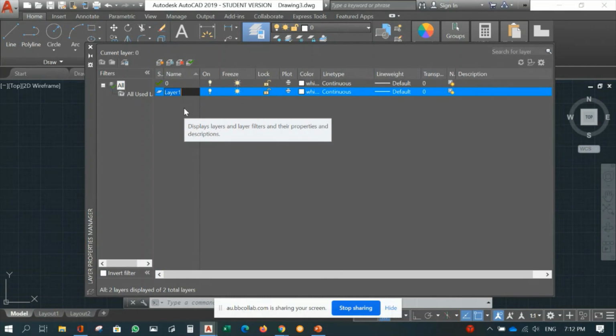This is very important, especially when you think of editing the drawing. Most important, with layers we can also apply the line width by using colors for each layer, and we can apply a line type for each layer. This will make our work much easier and more organized. All right, let's begin the first task, which is creating layers.